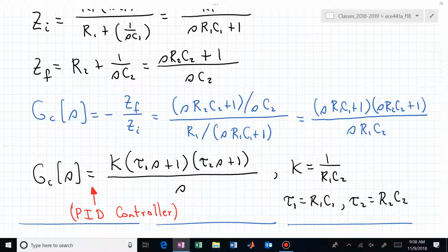We've talked about 2 poles and a 0. This is now 2 zeros and a pole. So we have all sorts of different lead-ins to the story that we might want to tell relative to a root locus or a controller. And now if somebody says, well, build me a controller, you can say, okay, I can build you a controller. You want a phase lead? You want a phase lag? You can build it out of op-amps and R's and C's. And here is a combination of those two, a phase lead and a phase lag.